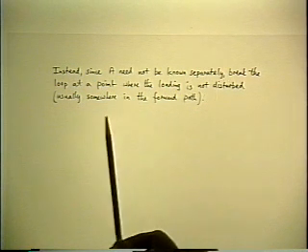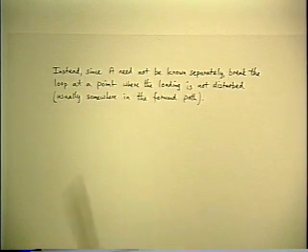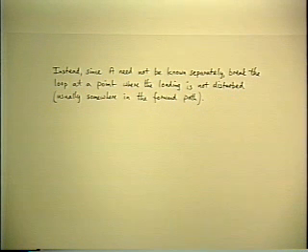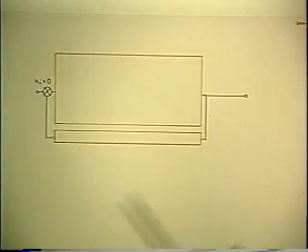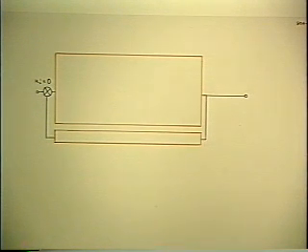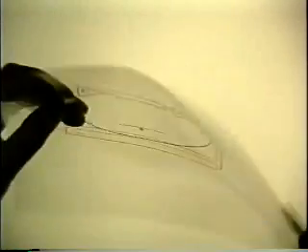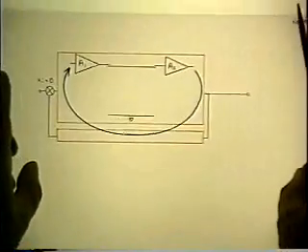It's very rare that you can find one of those points inside the feedback path, because the feedback path is passive elements, and the loading is usually significant there. So when you broaden the problem, you can look at a place where you can choose a better point where you don't upset the loading. So I'll redraw the picture.